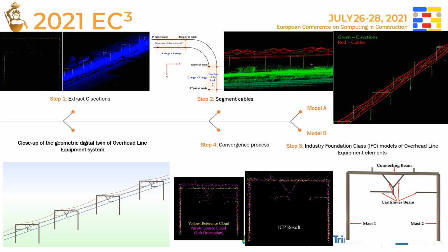Secondly, we extracted point clusters of cables using the RANSAC algorithm, which consisted of two refinement algorithms. These refinement algorithms first divided the whole point cloud dataset into near straight pieces and then removed the ground plane and finally upsampled the points on the cables to reduce the computational cost and to increase the detection accuracy.